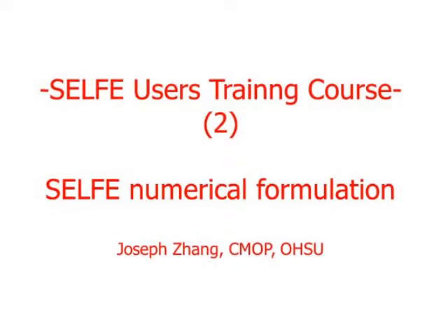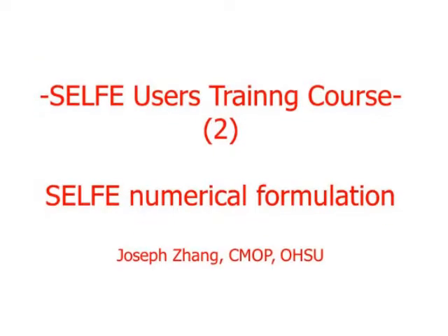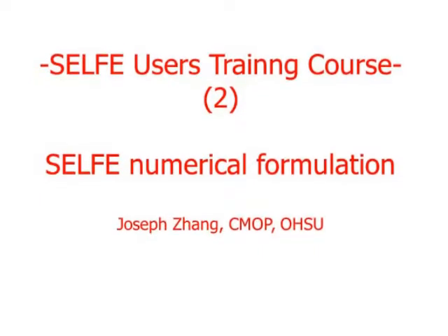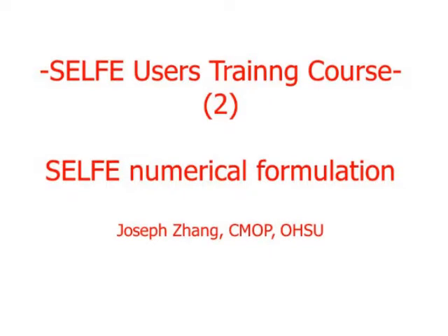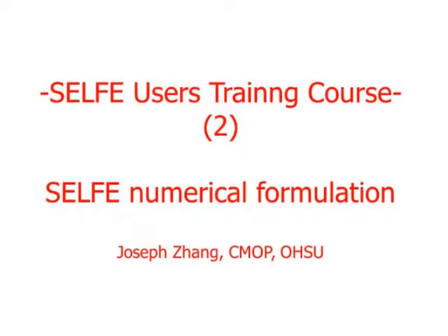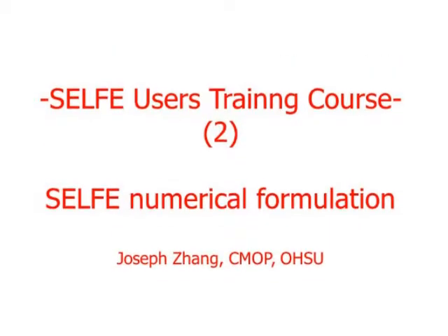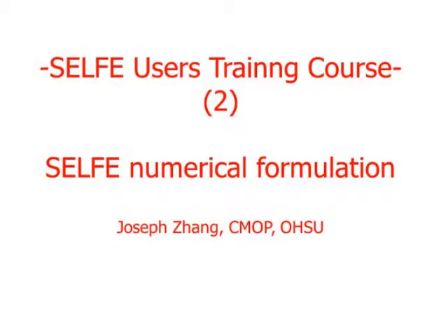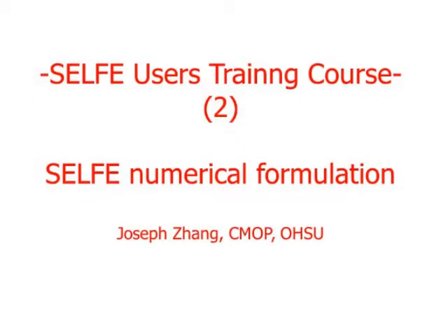Of course, in order to be a shape function, phi i must satisfy this consistency condition. Phi i means the shape function associated with a particular point i in space, and x_j means the coordinates of a particular point j. So phi i of x_j equals the Kronecker delta ij.